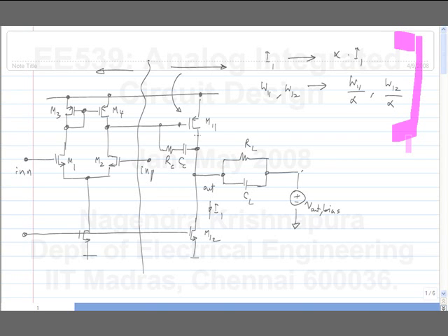There are two things. First of all, the parasitic capacitances will increase, so the small signal high frequency characteristic will not remain the same. That may stop you from doing this. And finally, maybe it's a very low speed circuit and you don't care about bandwidth at all. Then what's the limit? You will hit the sub-threshold region where this won't work anymore. Meaning, you reduce the current and increase the width, and the GM reduces. GM is not dependent on the aspect ratio in the sub-threshold region. Only in strong inversion is it related to the product of current and width. Once it reaches weak inversion, you can't do anything. That's the lowest current that you can design it for.